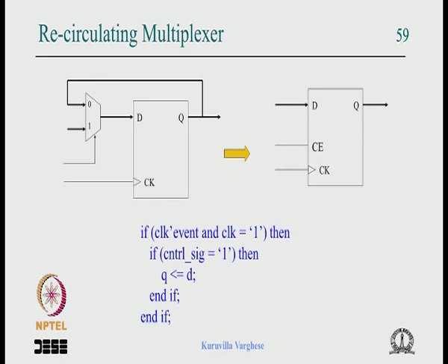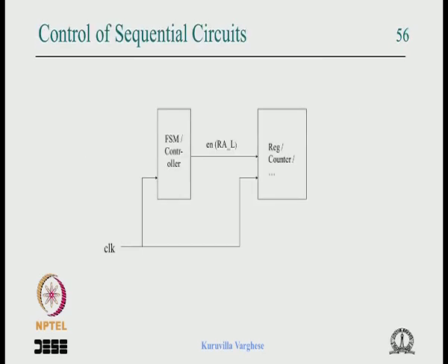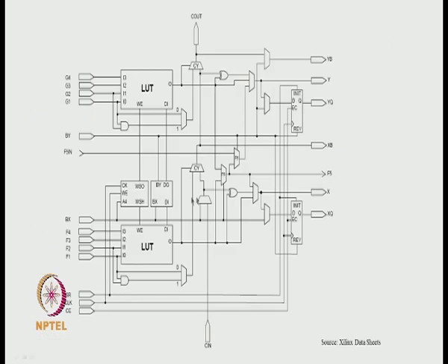So now let us see how the circuit gets mapped to this kind of architecture. One thing is that suppose you have a combinational circuit, you know that a lookup table is used to implement it. It can get combined if there are more inputs, like 2 4-input to 5-input, 2 5-input to 6-input and so on, and can be further combined or cascaded.